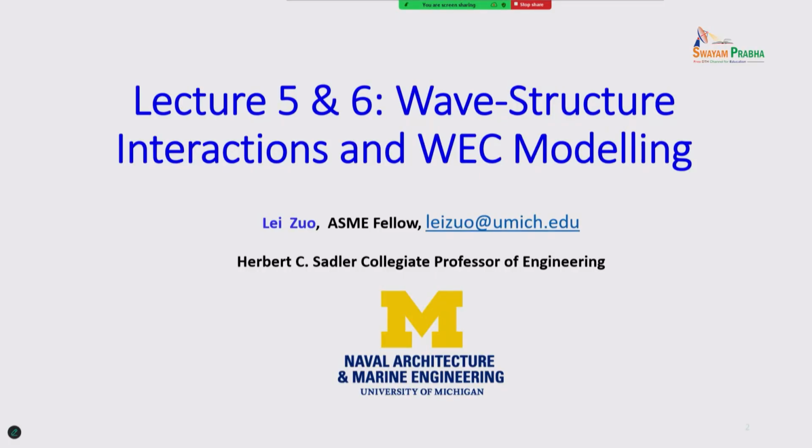So today we are going to see how the wave generates the excitation force. Basically, we are going to learn wave structure interactions and WEC modeling. Like yesterday we talked about the Cummins equation, and today we learn what the Cummins equation is.